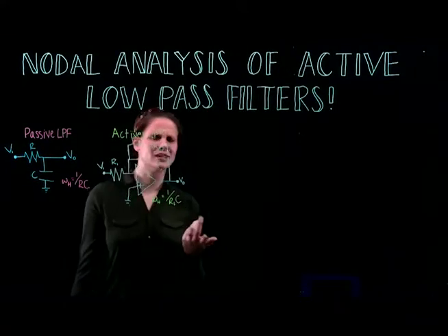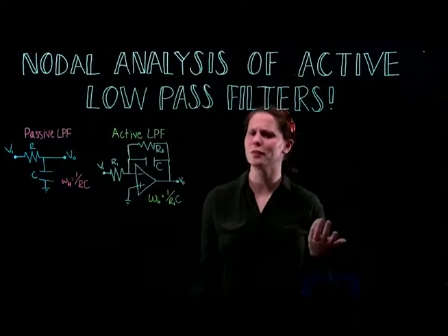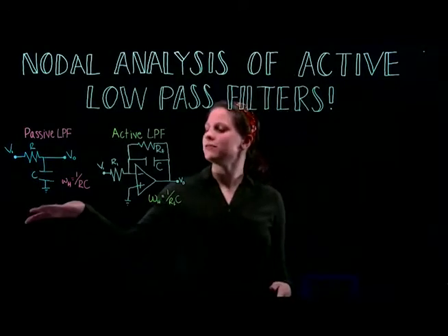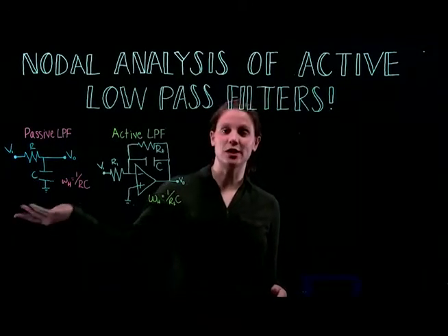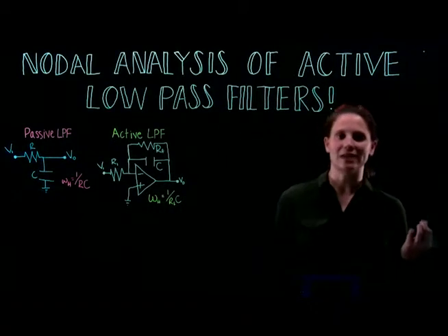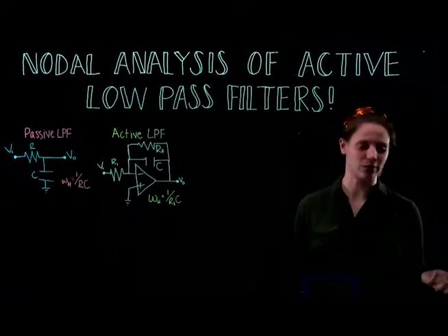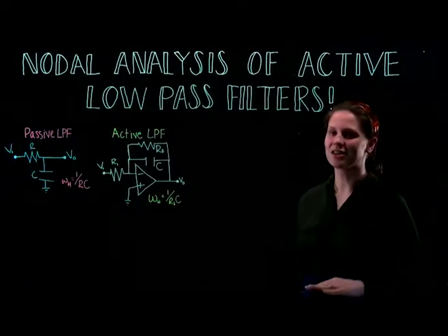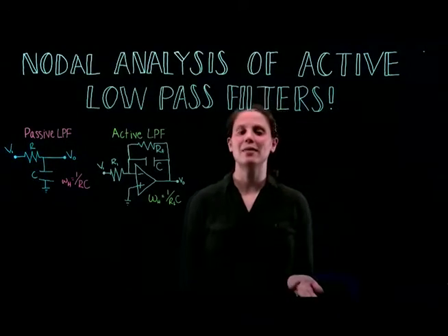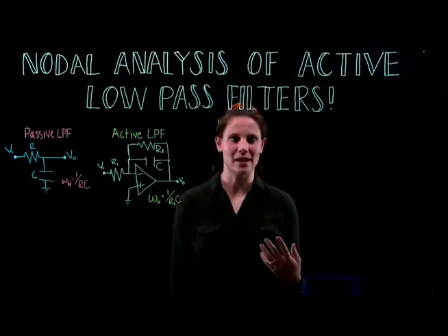So first, I wanted to talk a little bit about the significance of active low-pass filters over passive low-pass filters. Passive low-pass filters we're familiar with. This is the structure of them right there. Something that we run into with low-pass filters is that they result in attenuation, even though they effectively filter noise. Attenuation is a reduction of the output signal. Since biomedical signals are already low in amplitude, the passive low-pass filter isn't a great bet.